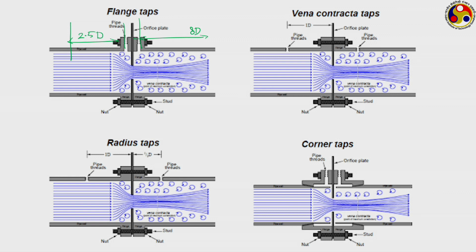However, it is a large distance that we have to consider, therefore the pipe itself needs to be quite long, and also whatever pressure losses the fluid may be encountering because of the pipe roughness and some other inhomogeneity in the channel itself, they will also get reflected, providing lots of noise in the measurement. So, pipe tapping is not a very popular one.